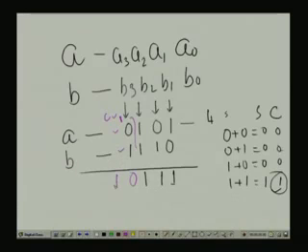So, this carry 1 will come here. Now, all the carries will go here. So, instead of 2 inputs, for the full adder I have to consider 3 inputs. That is why the full adder is defined as 2 operands and the previous carry. So, C we define as the previous carry, means the carry generated from the previous bits.